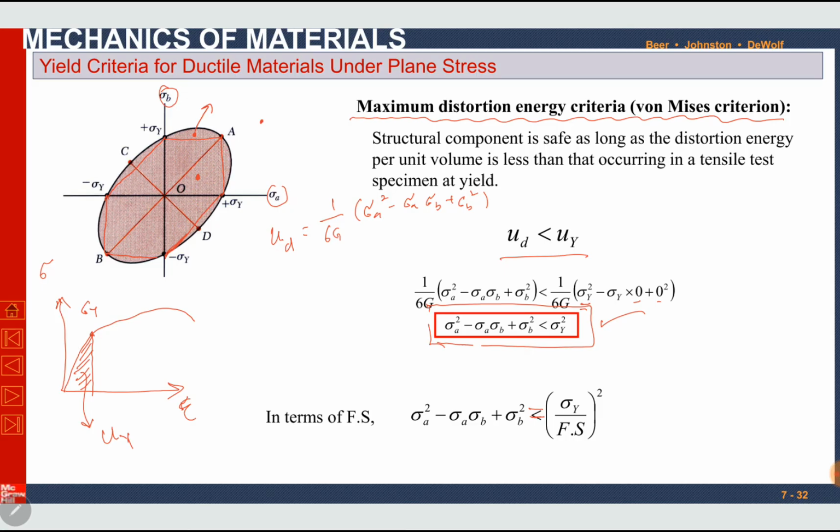But now we have to find which one of them is correct or actually applicable. If we see the literature, the von Mises criteria has been applied on ductile materials and it is effective. It means the von Mises criteria is safe, and it cannot be called a failed criteria. If von Mises is safe, definitely Tresca is safe, because the Tresca criteria is even more conservative as compared to von Mises criteria. So von Mises criteria can be applied. It is safe.